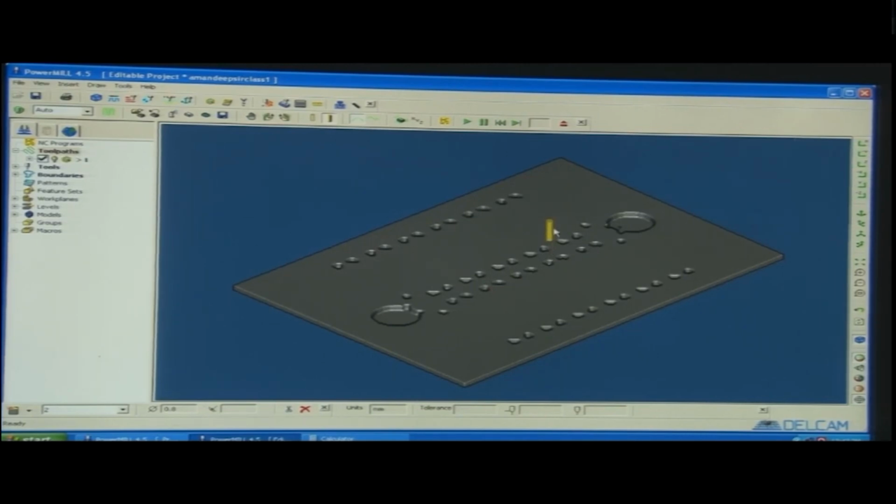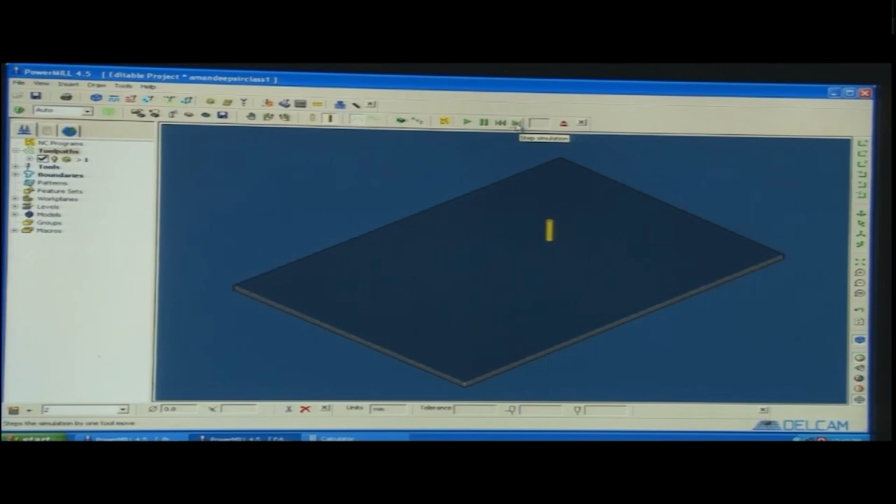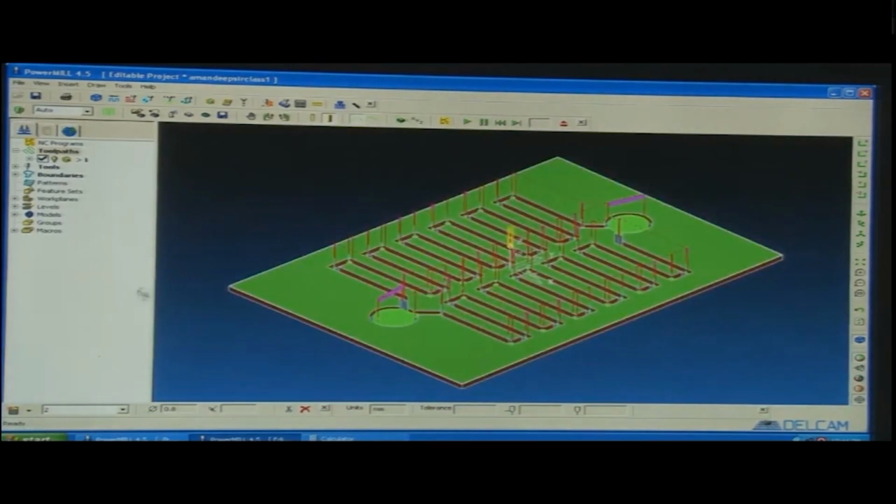So, lead in and lead out is being shown here. See the simulation again, stepwise. 1, 2, safe height is 5 mm, tool reference 3, now 3 mm and 2 mm, yes, now it has entered. Now, it is machining, then lift it up, lead out, then lead in, then lead out and so on, complete machining again. Okay, complete machining, complete plunging action.